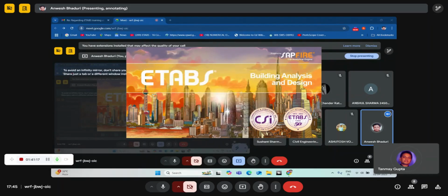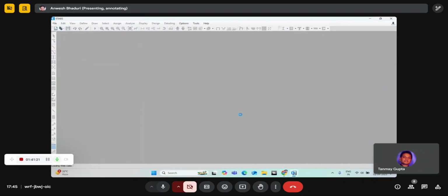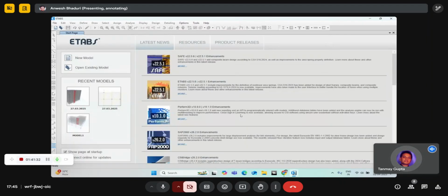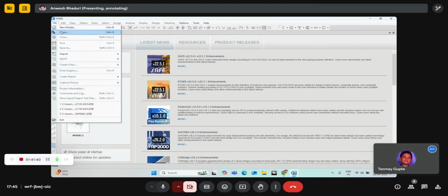Now, for your nonlinear analysis, you actually have to define your PMM hinges, then PMV hinges, like shear and moment hinges for beams. The hinges have to be defined prior to the analysis, as per our guess where the hinge can form.